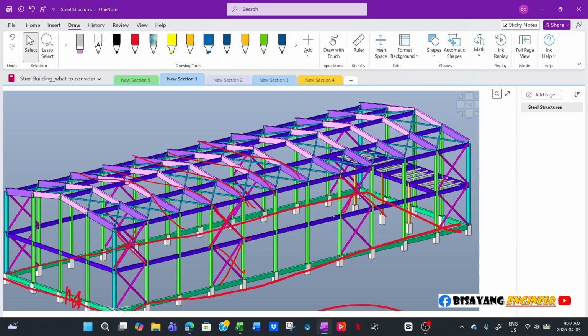Imagine the effect on operations. If you reinforce a foundation, you have to excavate, pour the concrete, and then wait until the concrete is cured. Even if you use early strength concrete, say 7 days, you still have 7 days lost in operations, right? That's why in new designs for some structures like this one, the engineers already consider higher loads just in case.